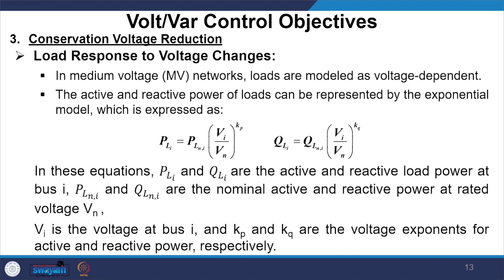Load response to voltage changes. Now, what is the relationship between the voltages and loads? Voltage dependent loads and load dependent voltage scenarios. In case of a medium voltage network, loads are modeled as voltage dependent.